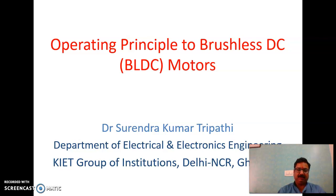Stator has armature winding, and these windings are excited according to the position of the rotor, and rotor position is sensed by the Hall effect sensor. So that part has been discussed in the earlier lecture. So in continuing that, we will discuss operation or operating principle of brushless DC motor.